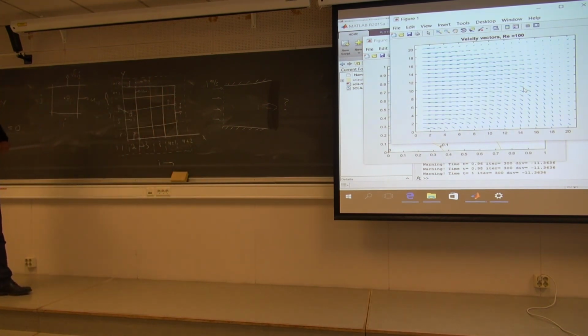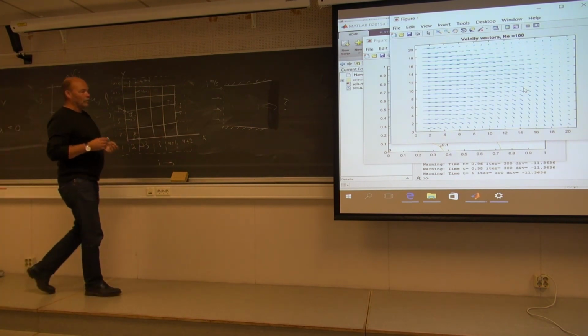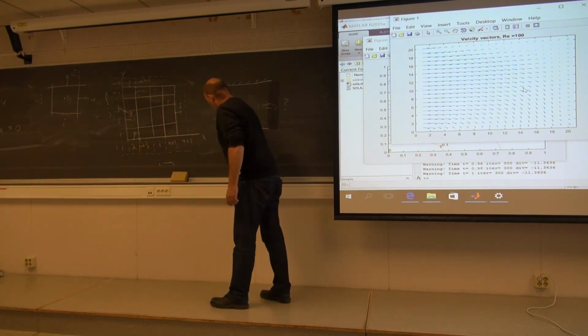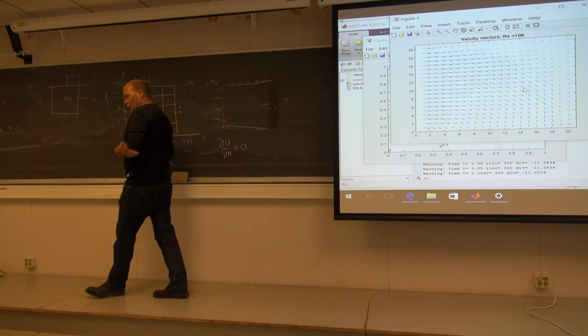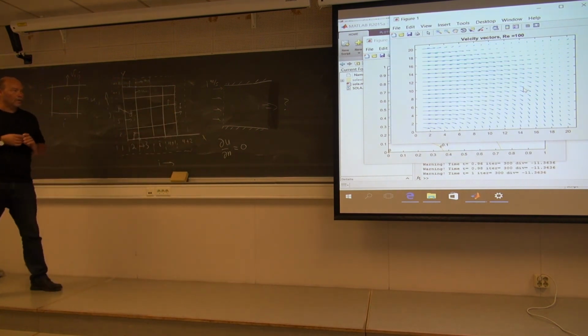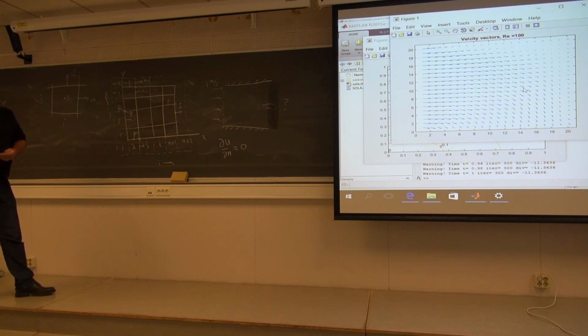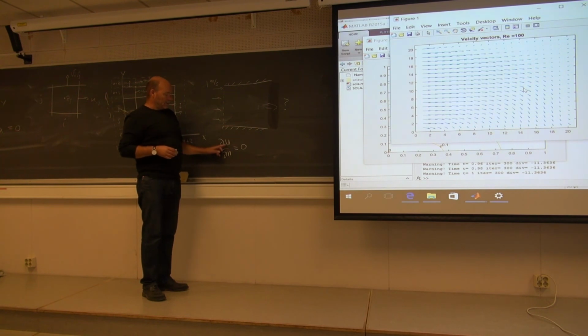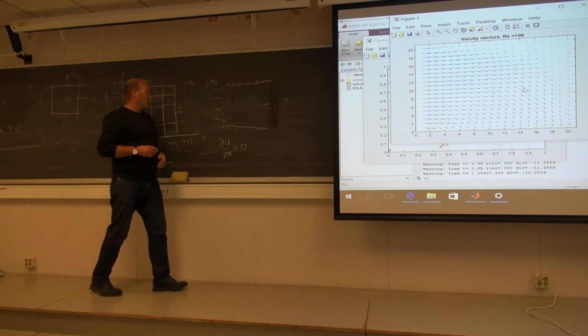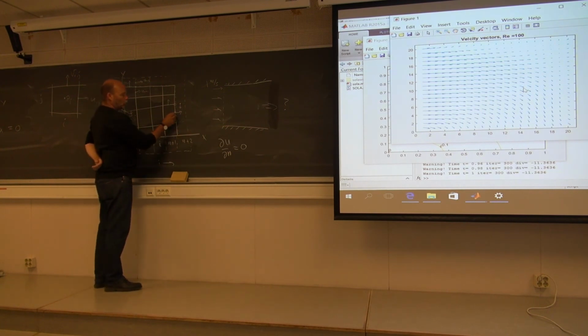So what do we do there? Well, we use the Neumann condition. That was du/dn equal to 0, where n now being the direction perpendicular to the wall, or here the outlet. Meaning this is then the x derivative of the velocity. So we have to specify something here, but I don't really know what. Then we say I want the derivative to be 0 here. Okay, I make it simple. I just put these two equal.